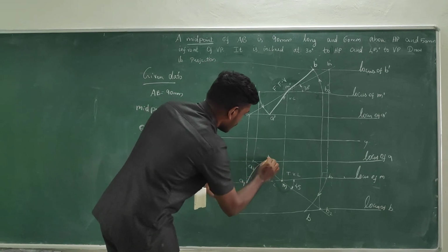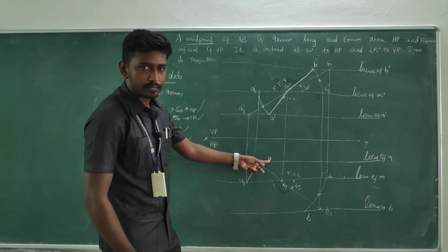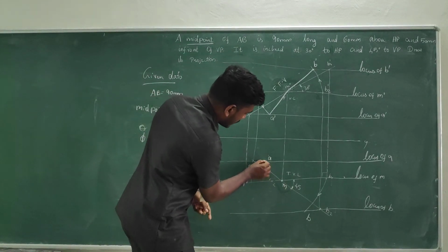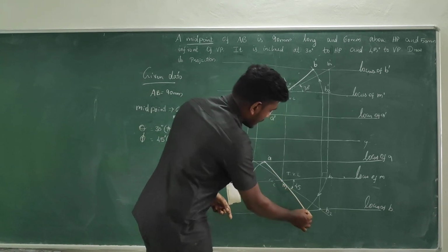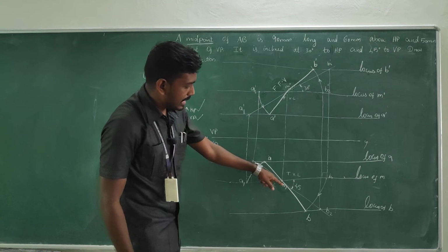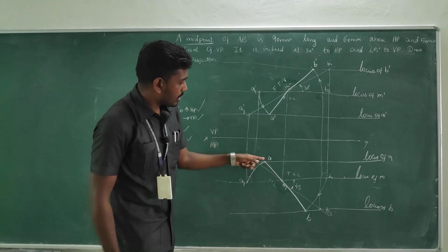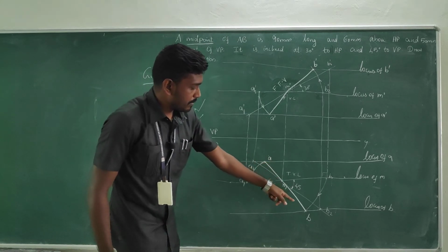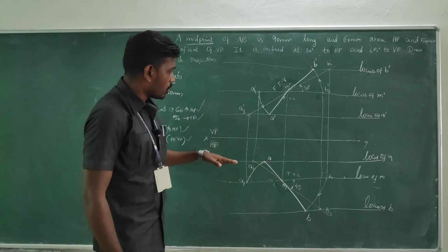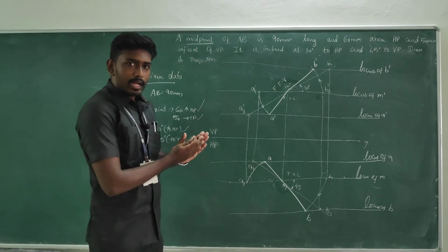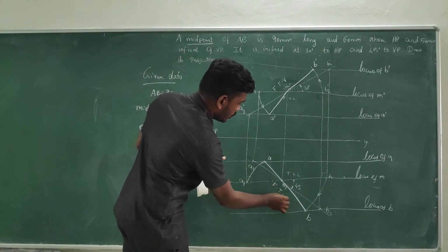So this will be the final point, so it will be A. If you connect a line joining A and B, it goes in a straight line and passes through the M if the profile is right. Okay, the line will connect A, M and B, and it is straight. Fine. After completing it, we know this is the final top view.